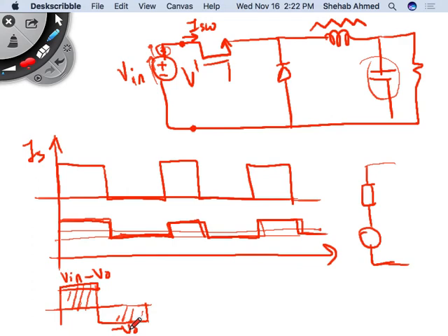Right? That's one thing. The other thing is it will cause additional ripple. Since the areas are not the same, you're operating this in transient now. If you're operating this in a transient, you're not operating this properly. It's not steady state operation of the inductor anymore, which means that the equation that we talked about cannot apply anymore. Right? So how do you solve this?